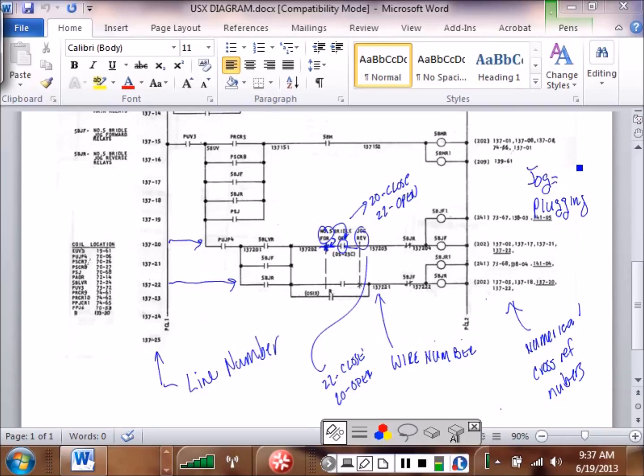Plugging a motor is when we reverse the motor before it comes to a complete stop. The motor is going to pull start current while it's trying to reverse itself. A lot of times if we don't size our overloads correctly, it's going to kick out. And it's not good on the motor, right?